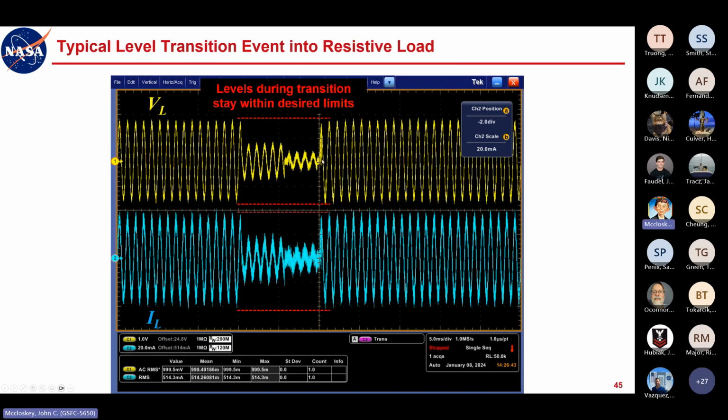But then we looked at a level shift, because of what you're doing with this, when we were in the lab on Wednesday, I'll demonstrate this a bit. When you go from one frequency to the next, you want to drop the level, then shift up to the next frequency, then bring the level back up to minimize any risk if you hit a resonance or the impedance starts to drop, where the level can shift pretty significantly going from one frequency to another.